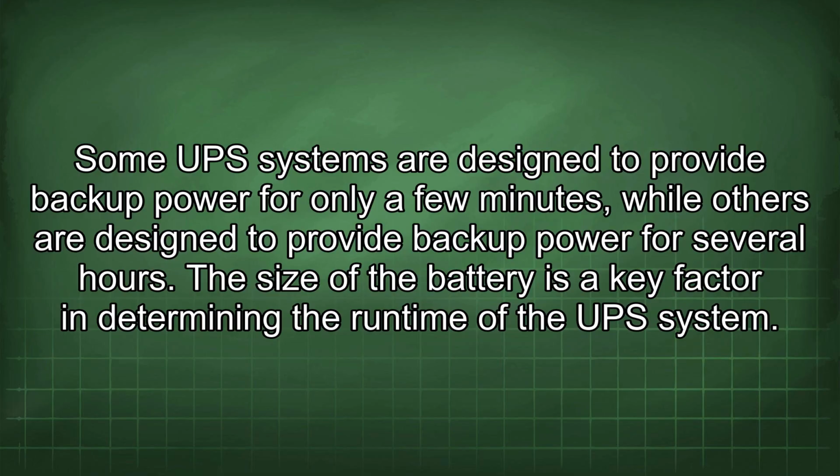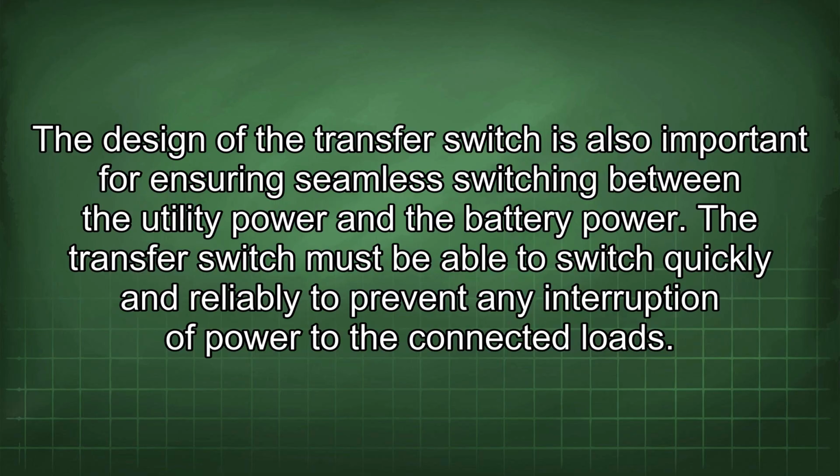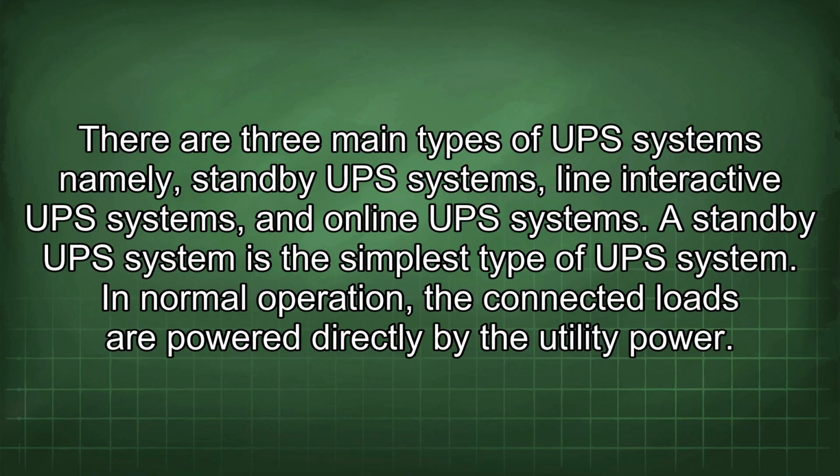The size of the battery is a key factor in determining the runtime of the UPS system. The design of the transfer switch is also important for ensuring seamless switching between the utility power and the battery power. The transfer switch must be able to switch quickly and reliably to prevent any interruption of power to the connected loads. There are three main types of UPS systems, namely standby UPS systems, line interactive UPS systems, and online